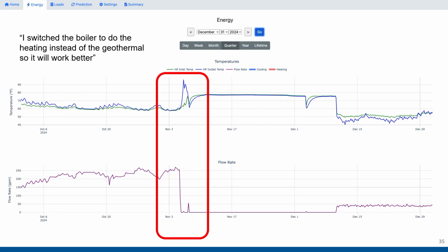Yeah, great question. So from what we've seen, it's not very feasible to measure the system COP, especially in a commercial application, right? You got to monitor every pump. If there's a ton of water to air heat pumps, you got to measure every one of those with electrical monitors, and then understand the thermal energy to get your total electrical energy as the ratio to that thermal energy. So not very feasible. But what is pretty feasible is you can put a BTU meter on that ground loop. And if you know that you're maximizing the use of that ground loop, you're just about at peak efficiency, right? Because you're utilizing that source as much as it could be utilized.